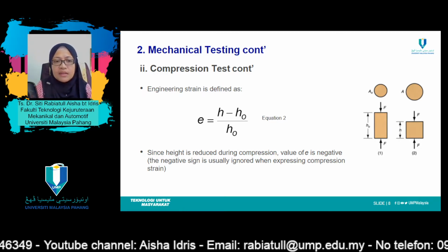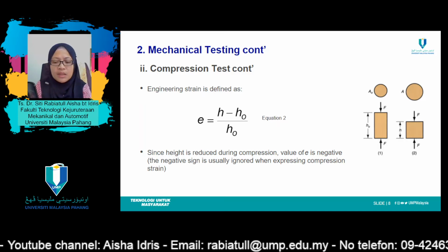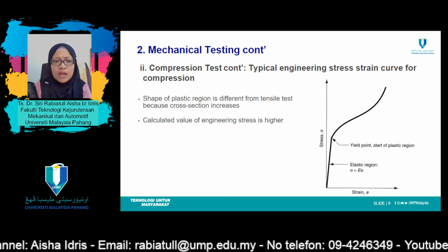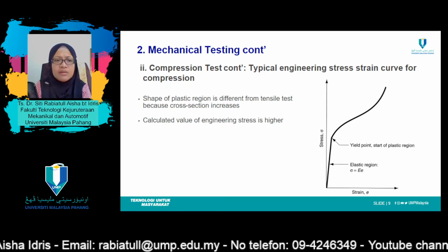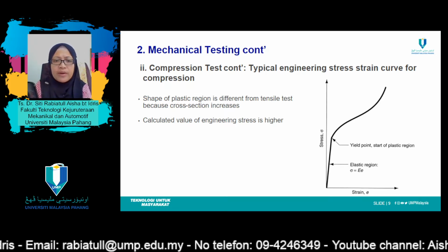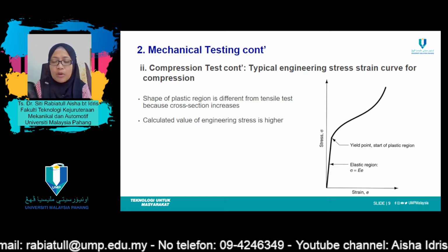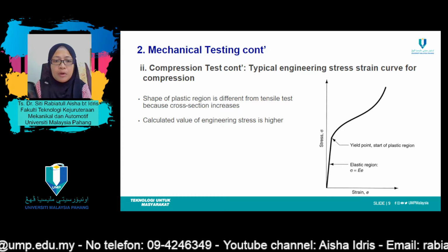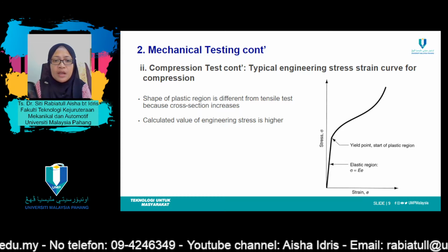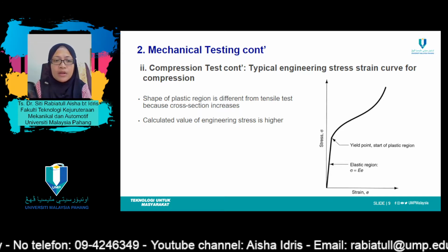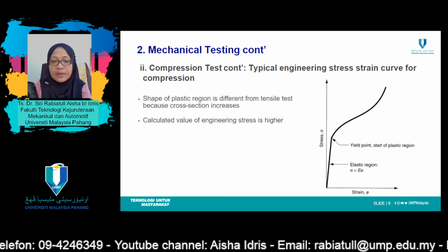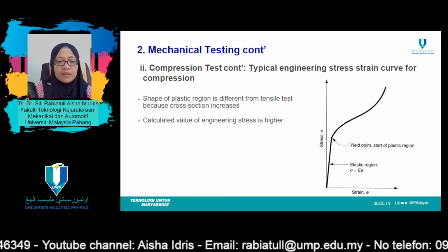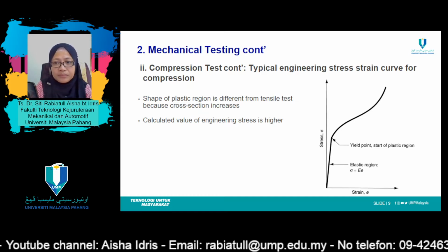Tensile tests are more common because they are easier to perform, and also for most materials in structural applications, very little additional information is obtained from compressive tests. Therefore compressive tests are used when material behavior under large and permanent strain is desired, as in manufacturing applications, or when the material is brittle in tension.